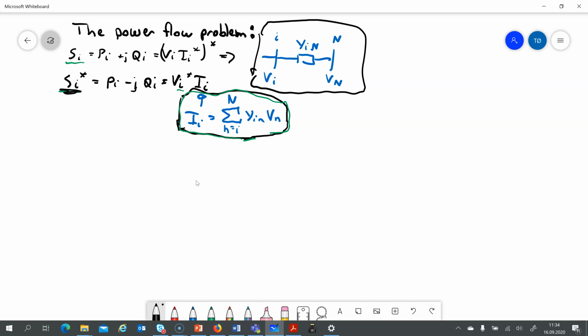Multiply that. And then from the generic outline I showed before, we can express the current as the product of the admittance times the voltage in every node. So this is a sum and the generic equation. We can also then have an expression for the Vi like this.